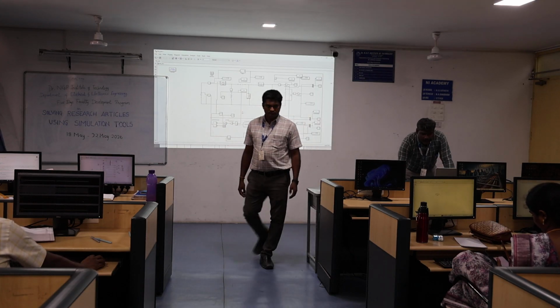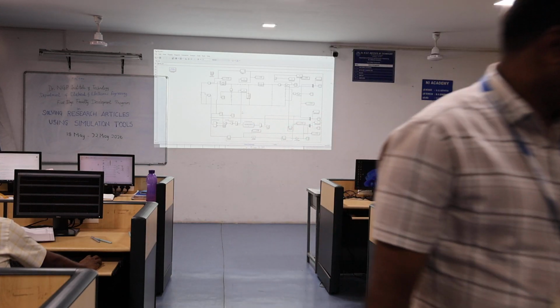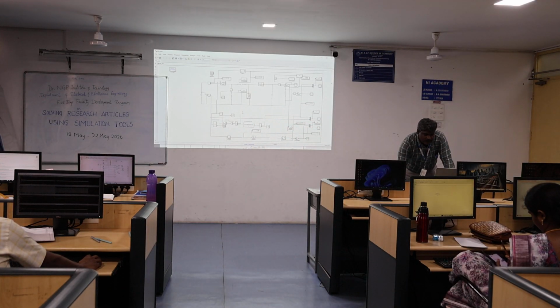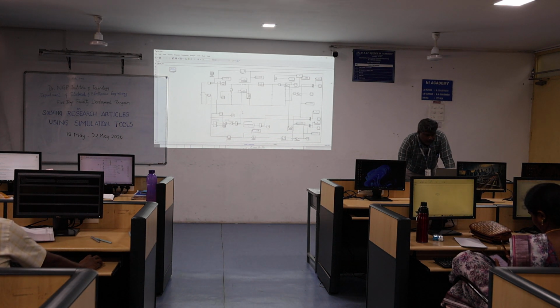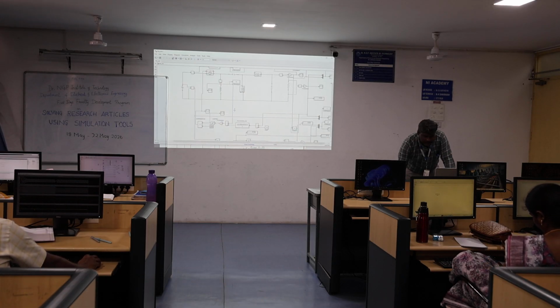So now for feedback, I want to regulate the output voltage. I am going to take the feedback from the output side. Here I mention minus 12 volt as the reference voltage. This is the PI controller for the outer loop, and for the inner loop I use a P controller for regulating the current. Then this is for the triangular wave. You know very well how to form it: you know the switching frequency, find the time period, then form the triangular wave. With a relational operator we compare and generate the pulse applied to the switch. Here minus 12 volt is represented as the reference value.